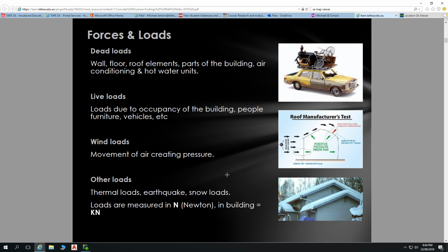So I've got the building over here. We've got a bit of bracing on there. Now obviously that's not going to be any use. It's bracing, it's a piece of plastic strap, and it's untensioned. It's very important that bracing is actually tensioned up, and I think I mentioned that previously.